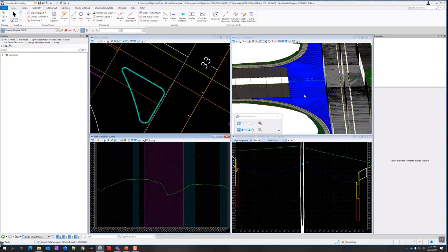So we have a surface here. All we really need to do is follow that surface. Now, again, for a drainage thing, maybe you want to actually build it up so you can force it to go higher in this location rather than having this dip. But for a starting point, we're going to build it from the surface. So we'll just clip it right there on the surface.